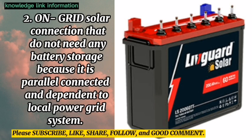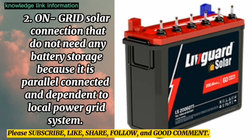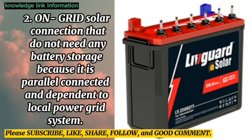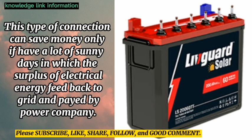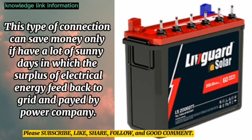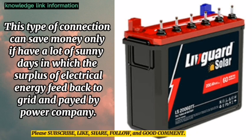Number 2. On-grid solar connection does not need any battery storage because it is connected in parallel and dependent on the local power grid system. This type of connection can save money if you have a lot of sunny days, in which the surplus electrical energy is fed back to the grid and paid by the power company.